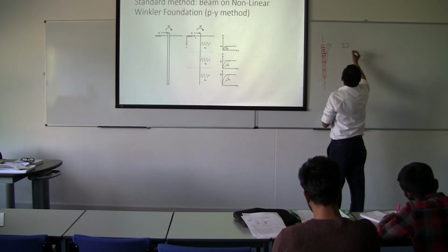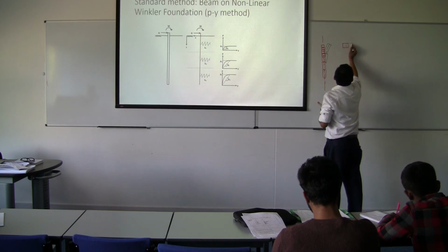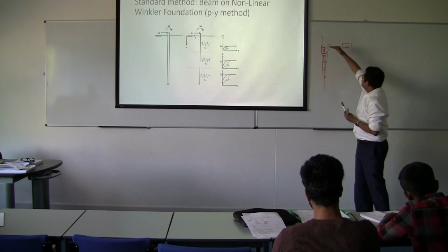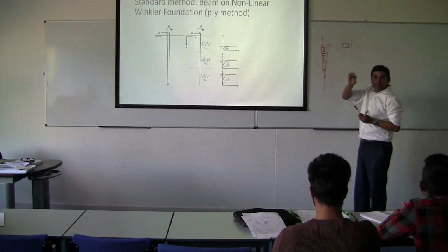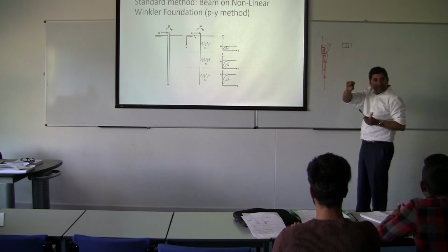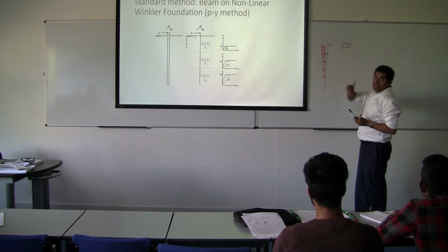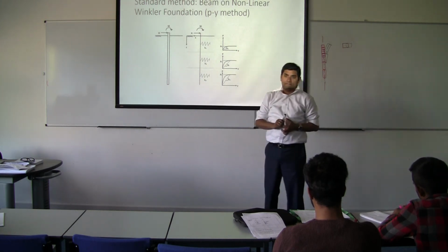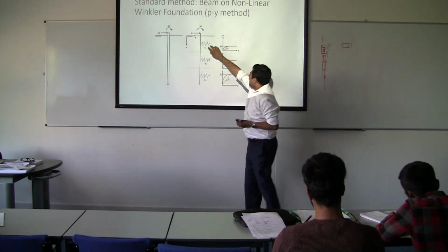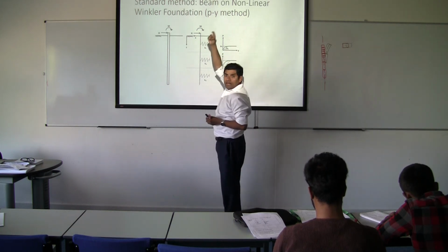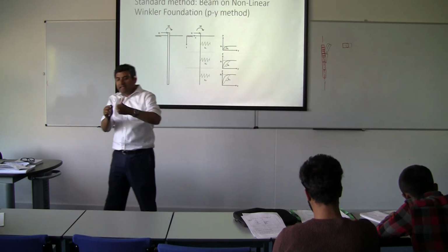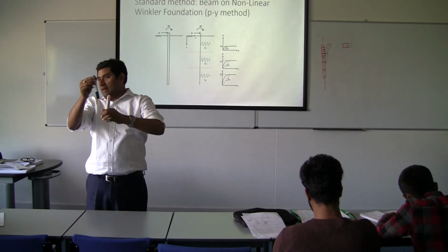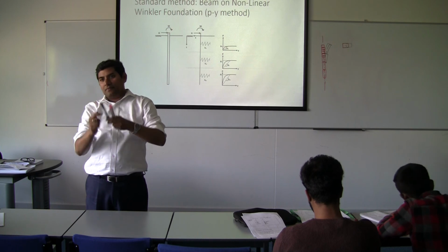So it now became like that, right? So there is a series of all these elements, and each element moves sideways, right? And we represent this by a spring called P-Y spring, right? So I can make it every half a meter. So I'm assuming that it's a series of elements, right? And each has got a spring attached to it.